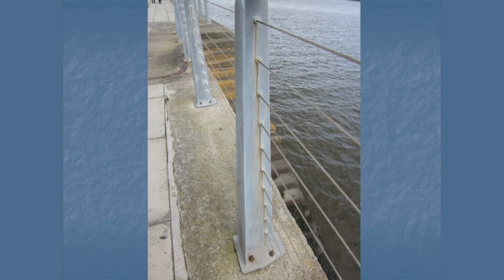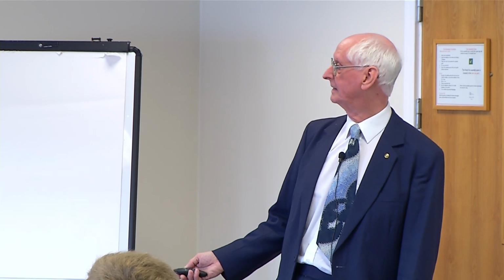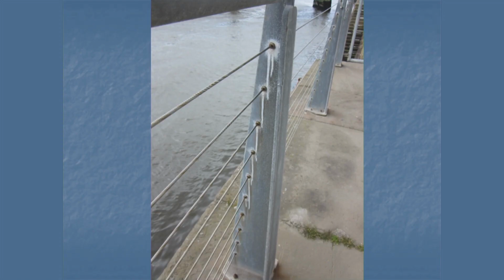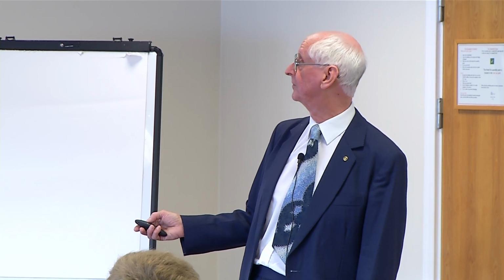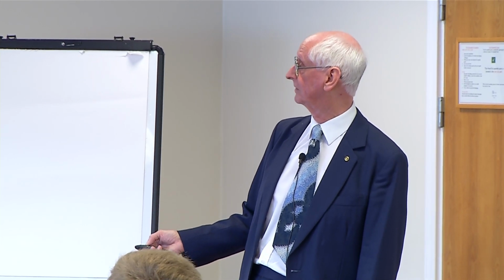And what happens? Of course, you get rough weather, you get salt spray going up there, and the salt gets on, the water comes down, it goes past the collar, and this starts a corrosion cell, and you can see the corrosion now running down from each one of these. But that wasn't a very good idea anyway, because these things are, the white plastic, a little white plastic collar. And as you know, plastic degrades in sunlight, especially if it's not black plastic. And these corrode and they degrade, and you can see the corrosion cell formed round here and literally running all the way down.